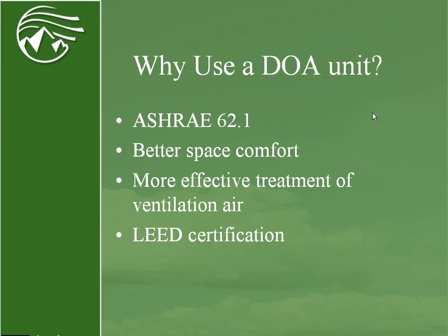So what is that dedicated outside air unit going to do for those spaces? What's it going to do for a gymnasium? Well, first of all, it's going to help you attain ASHRAE 62.1, but it's also going to give you better space comfort because, like I said before, we're decoupling or separating the ventilation heating and cooling requirement from the building heating and cooling requirement.